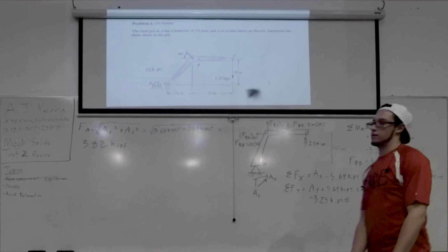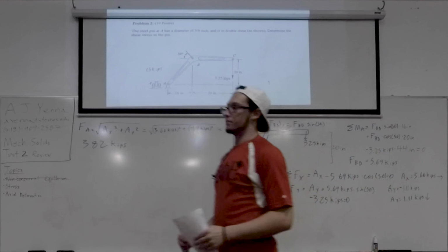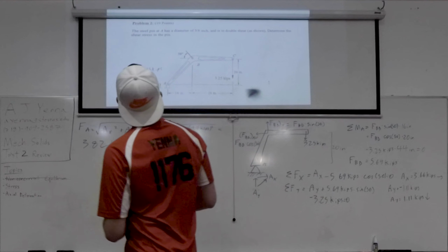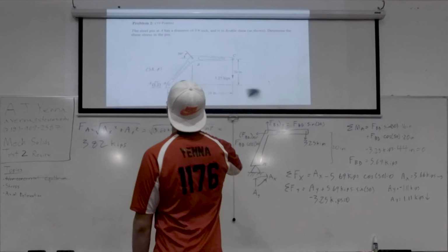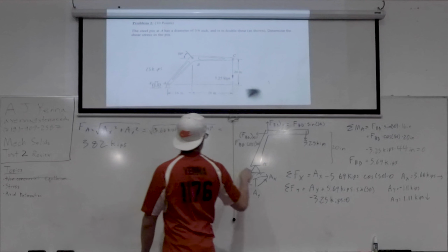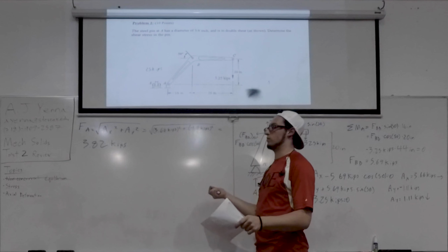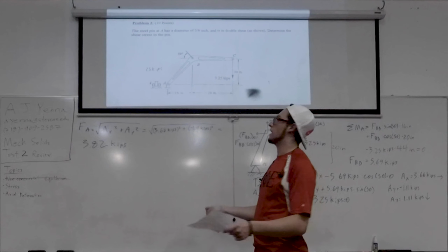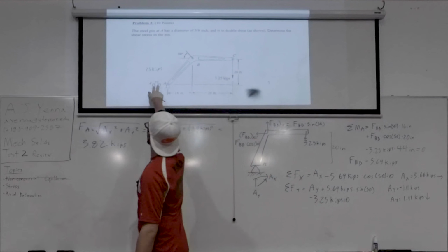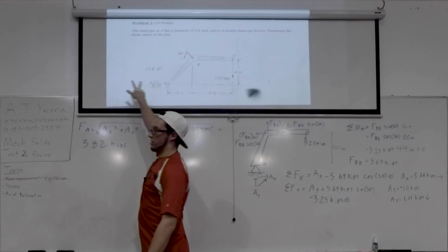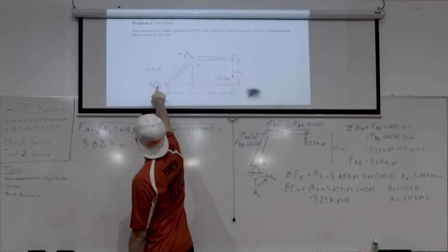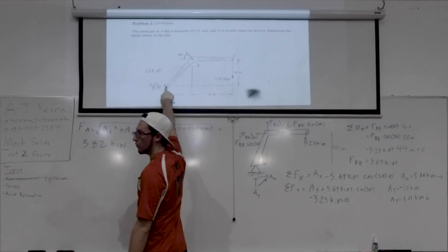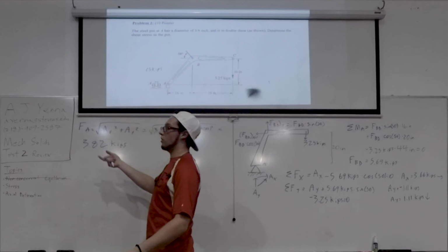Yes. So if they're asking for the normal stress, they would all use the same force? If they were asking for the normal stress, yes. Then for this one, the shear force that they gave you can't solve for normal force in this problem because of the way it's drawn and asked. Again, normal stress would be caused by this, so this would have had to have been drawn from a different angle, and they would have had to give you some force here, which we don't know.